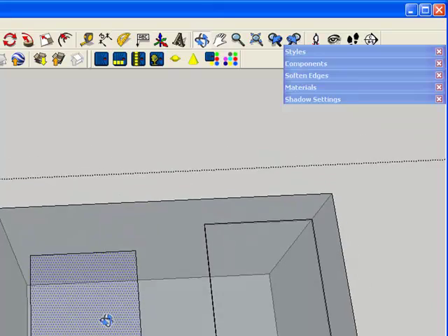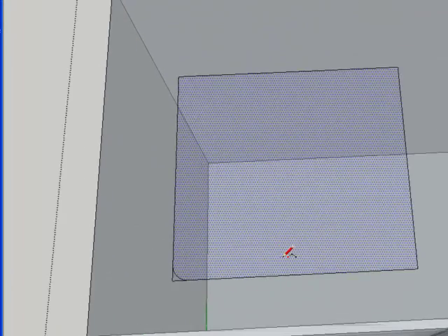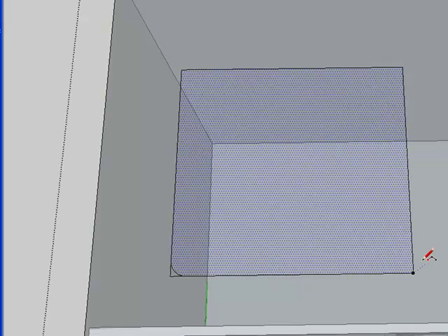And if, for instance, I was making a sink, this would have rounded corners. Now, if you want to round corners and make sure you get them the same roundness on all corners, after you draw this, when you come over and see where the green dot is, that's where the arc meets the straight. Let it sit there for a moment, and then if you bring it across, see how I get that dotted red line?